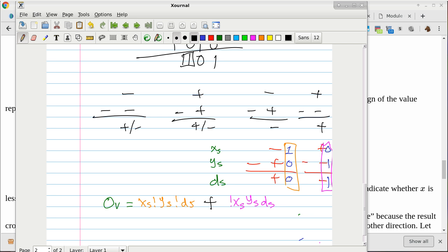But we need to boil these down to logic gates because we know how to do logic gates. So the orange part of the logic gate deals with the first part, where we subtract a positive amount from a negative amount, but somehow end up with a positive amount. That is telling us that we have an overflow situation. And then the magenta is the other one, where we are subtracting a negative amount from a non-negative amount, but somehow we end up with a negative amount, which is also indicative that we have an overflow situation. So now we convert everything into a logical expression.